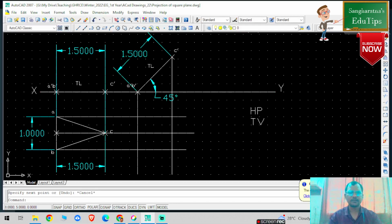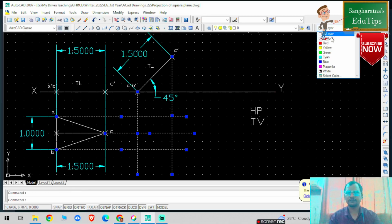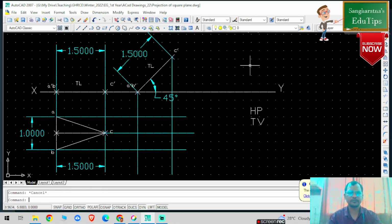Now mark the point here. Convert these projector lines into cyan color first. So I'm selecting this, click on unsnap. Converting into cyan color, press escape. Now mark the point. So these are the A and B vertical projections. This is my point A, this is my point B, and this is my point C. Immediately join these three points with a straight line.